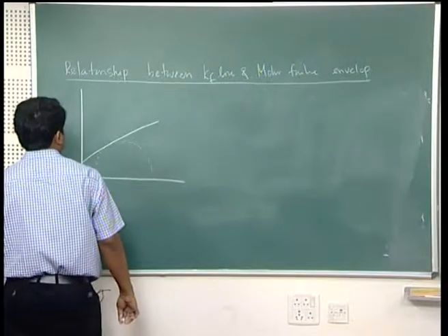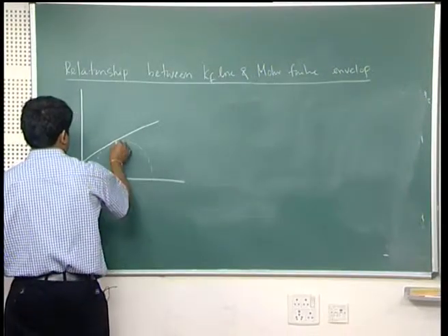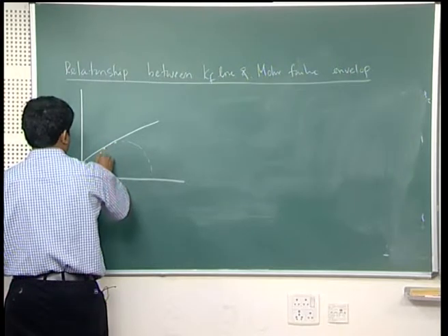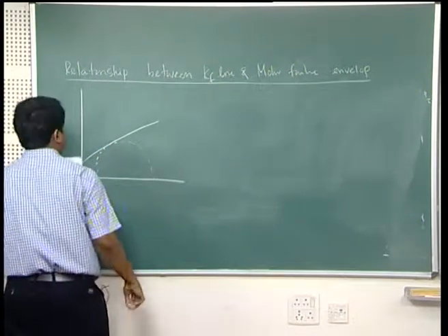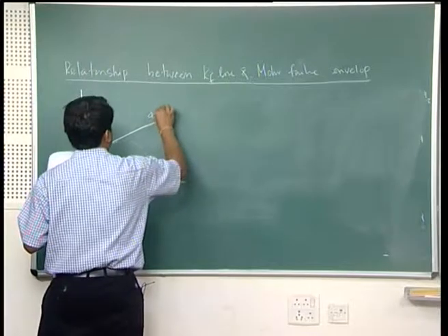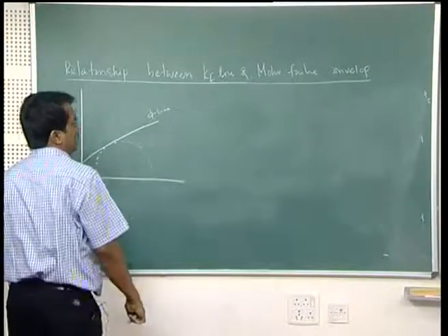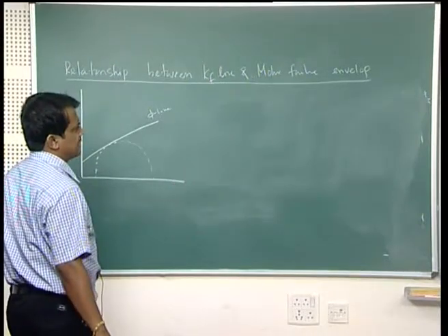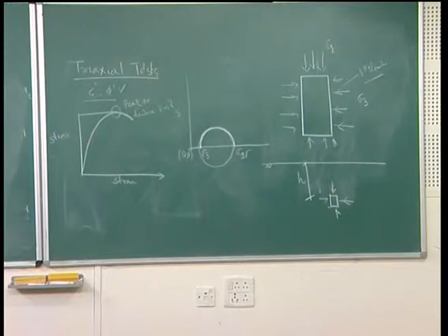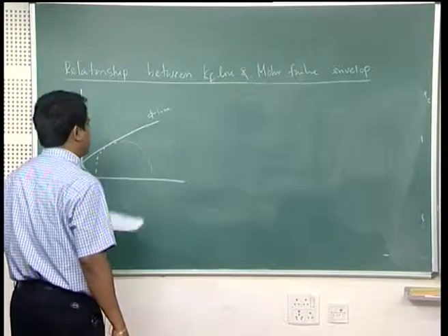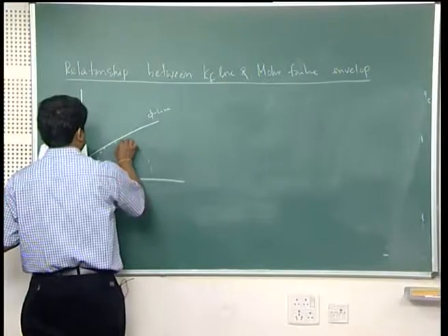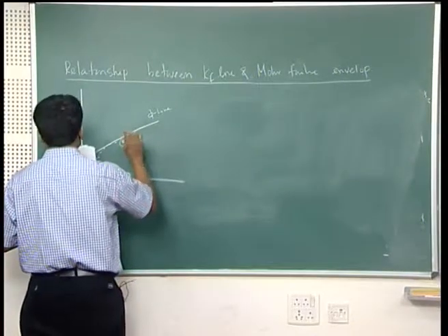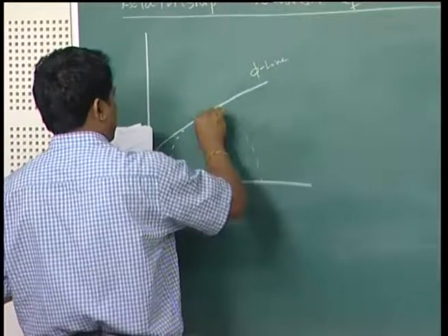The tangent which touches your Mohr circle is the phi line or failure line that you get from your standard triaxial test for 3 sets of confining pressure, sigma 3 1, sigma 3 2, sigma 3 3. But here with P Q and the stress path, the locus of these P Q points will be around the middle.